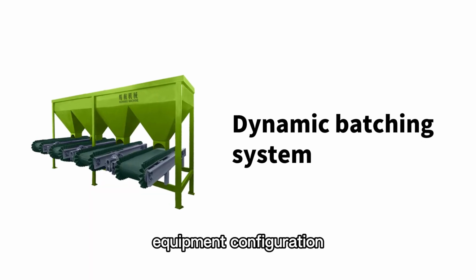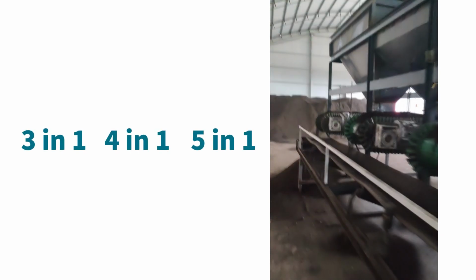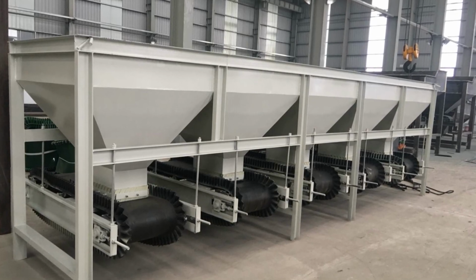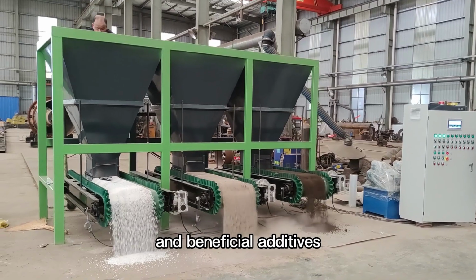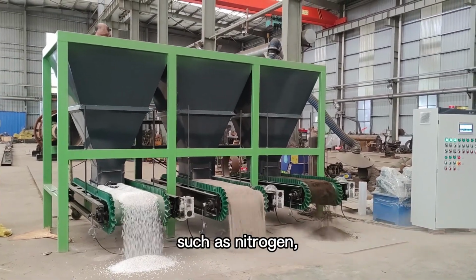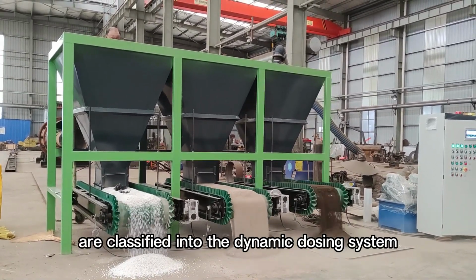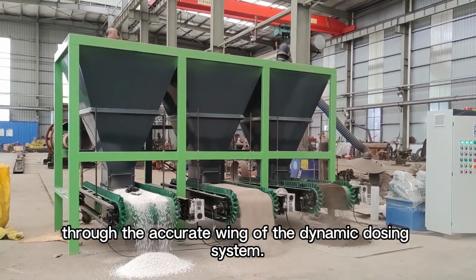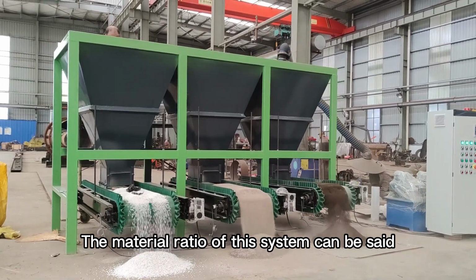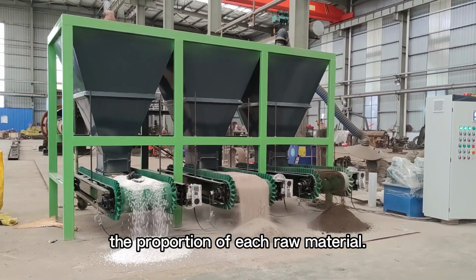Equipment configuration. Dynamic batching system. Machine type 3-in-1, 4-in-1, 5-in-1. The crushed organic materials and other powder excipients, such as humic acid, bentonite, and beneficial additives, such as nitrogen, phosphorus, and potassium, are classified into the dynamic dosing system and automatically dosed through the accurate weighing of the dynamic dosing system. The material ratio of this system can be set according to the process requirements, the proportion of each raw material.